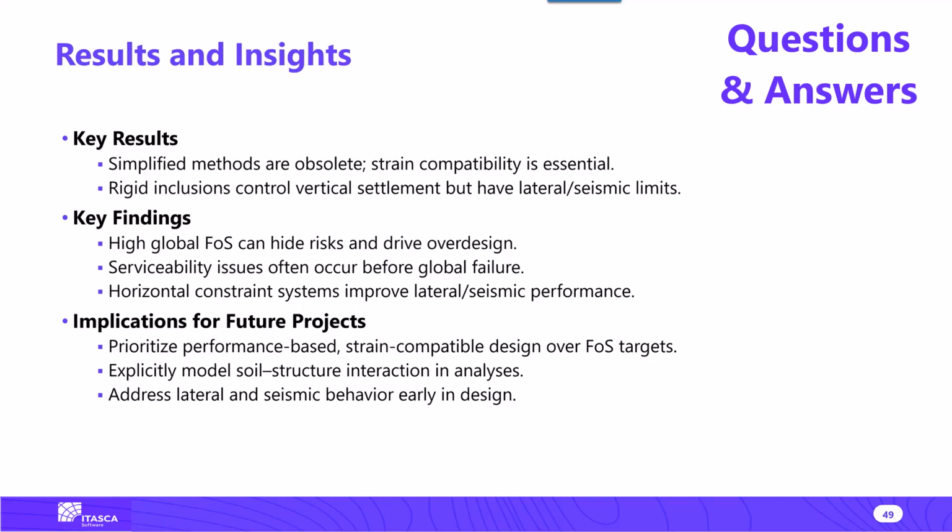Typically, you have a big spike of pore pressure, and then that pore pressure tends to dissipate. So you have a little bit of a consolidation horizontally, but in this type of material, it's not that relevant. If you have a loose sand, on the other hand, the horizontal densification that you're getting can be more important. Then at that point, I have two options. One is to model the process explicitly. Essentially, I impose a strain related to the volume ratio of the ground improvement in such a way that I can modify the horizontal stress.